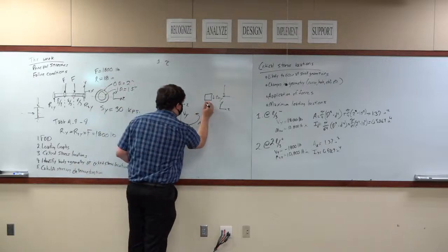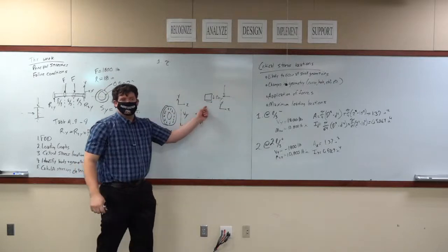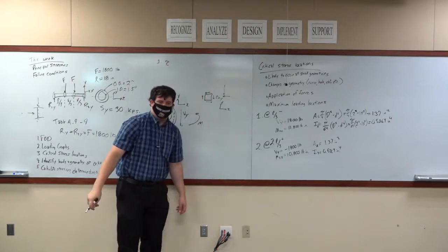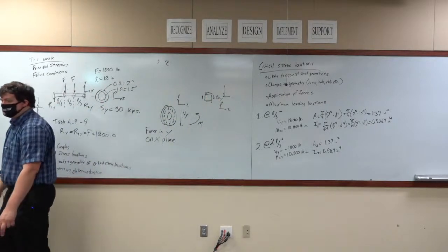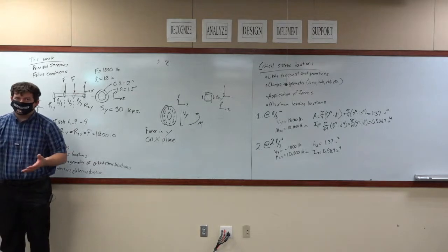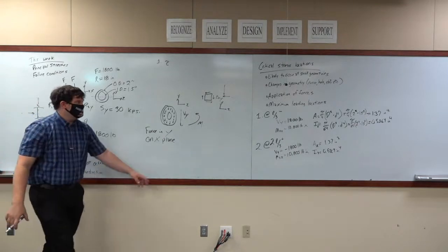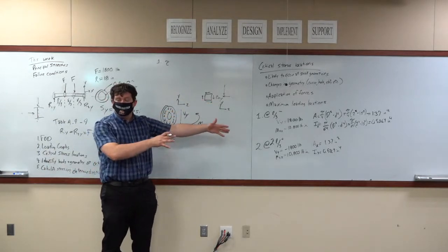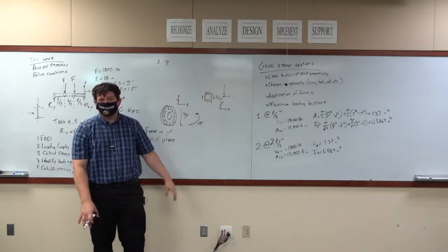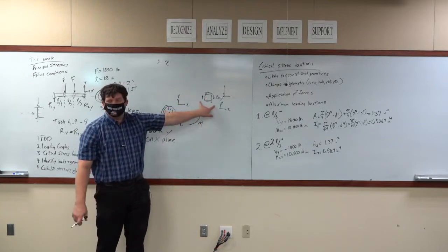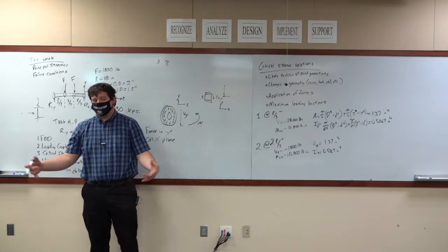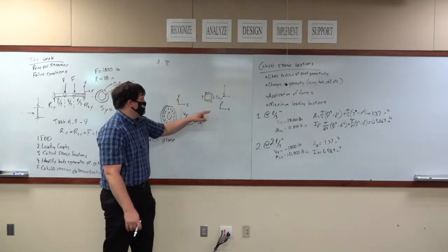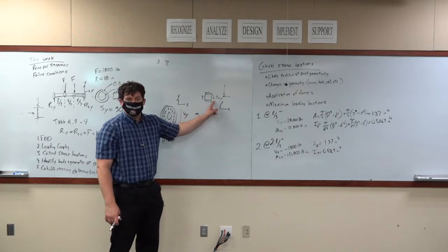Now, to counteract that, you have a force here, a force here, and a force there, because that's what shear stress does. You apply one force, you end up with 4 on your unit cube. These two counteract each other because that's how it transmits through the element. These two exist to counteract the moment that is created by the first two being transmitted through the element. So, these 4 forces, this is in the Y direction on the X face.